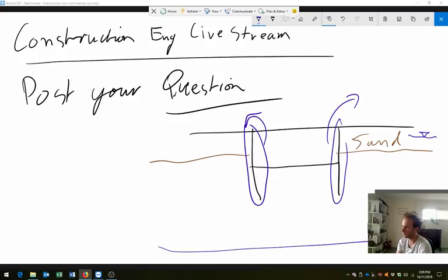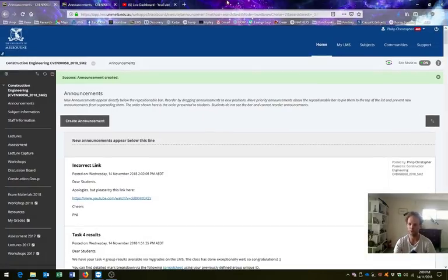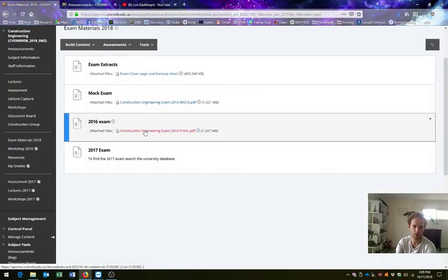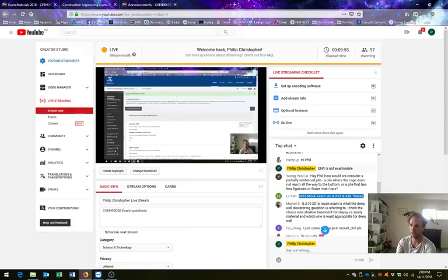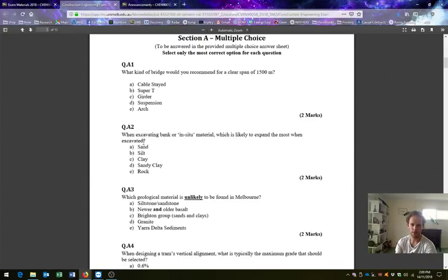So I'll go to LZ's questions now for the 2016 mock paper. So let's bring this up. Okay. Exam materials, 2016 mock exam. Great. And you are after question A2. So A2, when excavating bank or in situ material, which is likely to expand the most when excavated? Okay, so rock's going to expand the most. We didn't really cover that as much this year, but yeah, rock, because it doesn't stack really very evenly, it's got lots of voids, that will expand the most out of those materials.